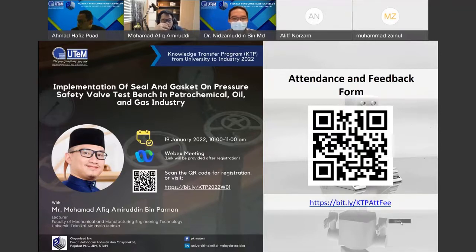So if the installation during the test is not proper, the vibration will be high. To avoid this, before we do our test, make sure that the clamping system and the subject testing are locked very carefully. So this vibration will be reduced.